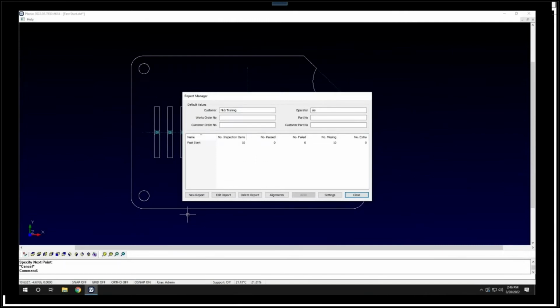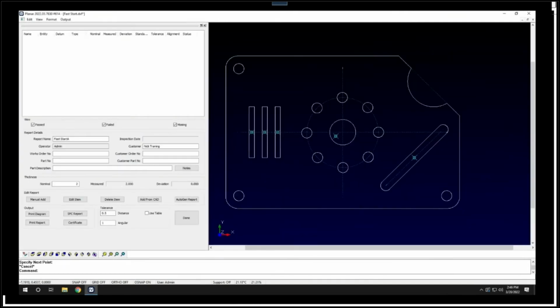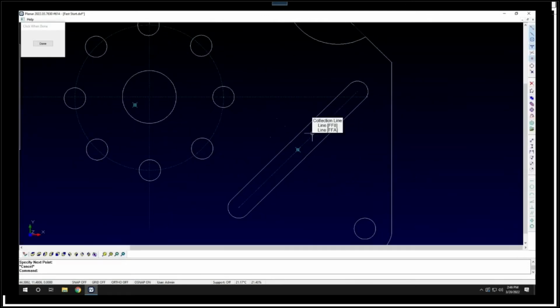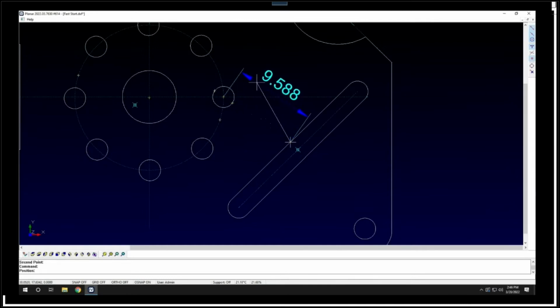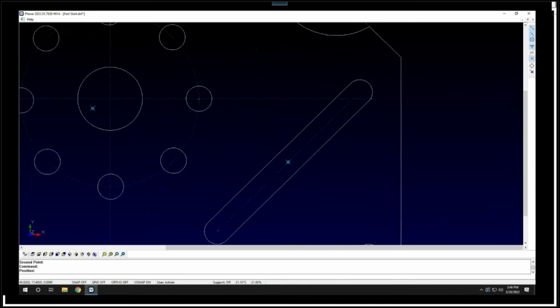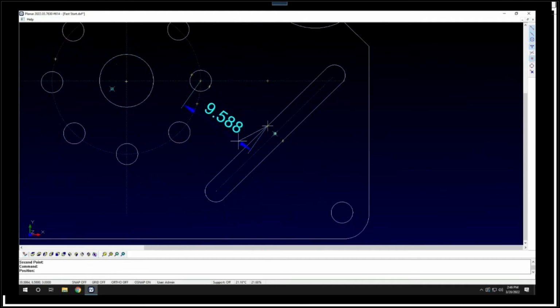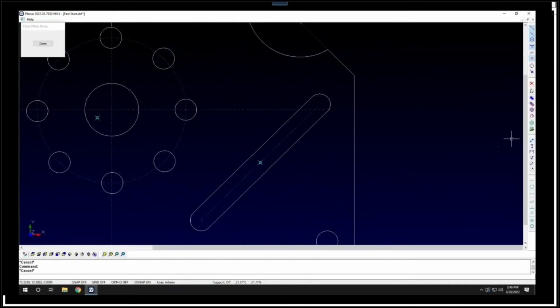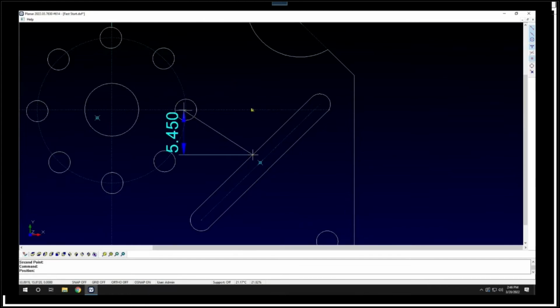Now, let's talk about that angle measurement we were chatting about. Let's say you guys have a dimension where you need to know the distance from this line here to this circle here, but it needs to be aligned to this feature. As you can tell, when I drag my linear box up and down, it's not aligned to this slot at all. So to do that, we can go create a vertical dimension from the midpoint of this line to the center of this hole.